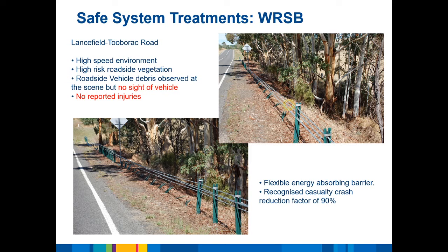All of the steel post parts, you can see here, they're designed to break away. They have a little sleeve that gets put in the ground, so you can basically just come along, pull the old broken piece out, slip a new one in, reset the wires, retension it, and it's good to go.